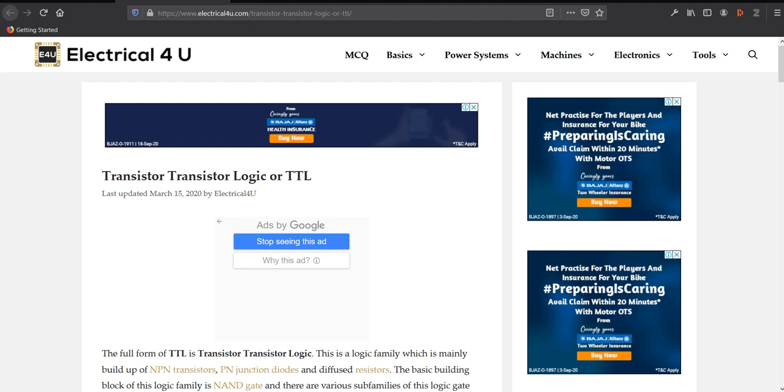Yeah, correct. So here, logic 1 is given, so preset will basically take it as 0. It is disabled, you can say. Based on this X, first we will draw the output Q of the first flip-flop, take it as D for the second, and then draw the output waveform. So essentially, whenever X is going 0, the output of the first flip-flop will go to 1 irrespective of the clock, whereas the final output will depend on the clock. The intermediate output will go to 1. So we will discuss the solution here.